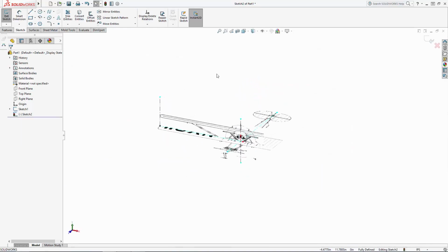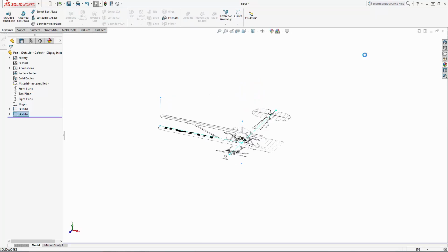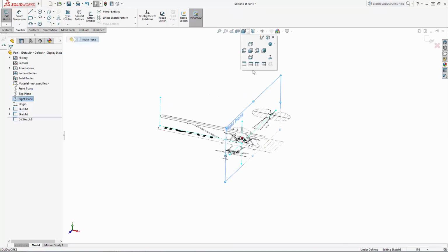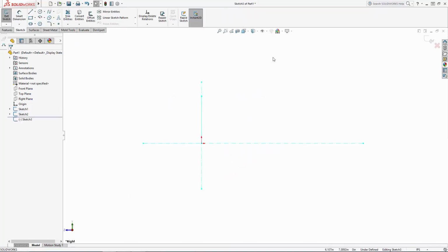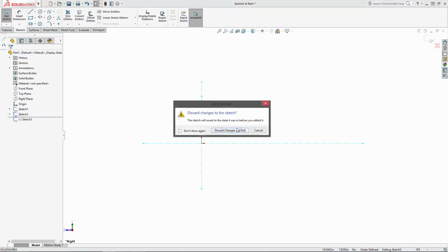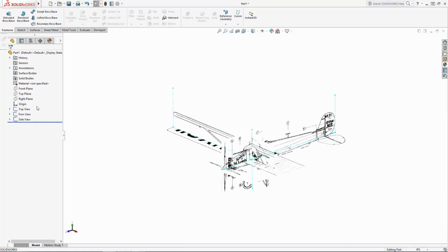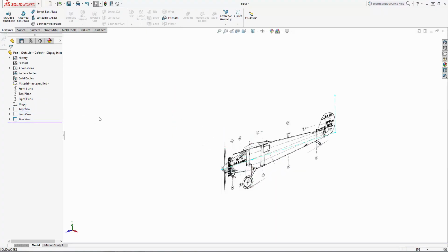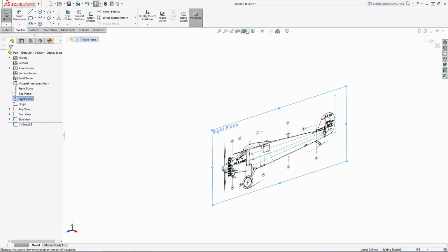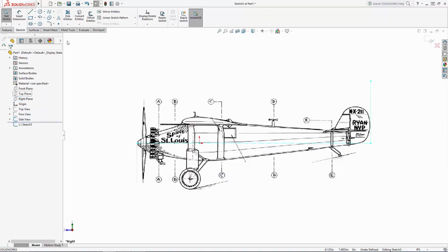I'll go ahead and follow these same steps to drop in the side view, taking my time to line the image up to the other views. I'll see you on the other side. Now you can see how these 3 views are nicely aligned with each other, so we can start adding in some construction sketches. We'll first draw on our side view to sketch out the foundation for our loft guide curves.